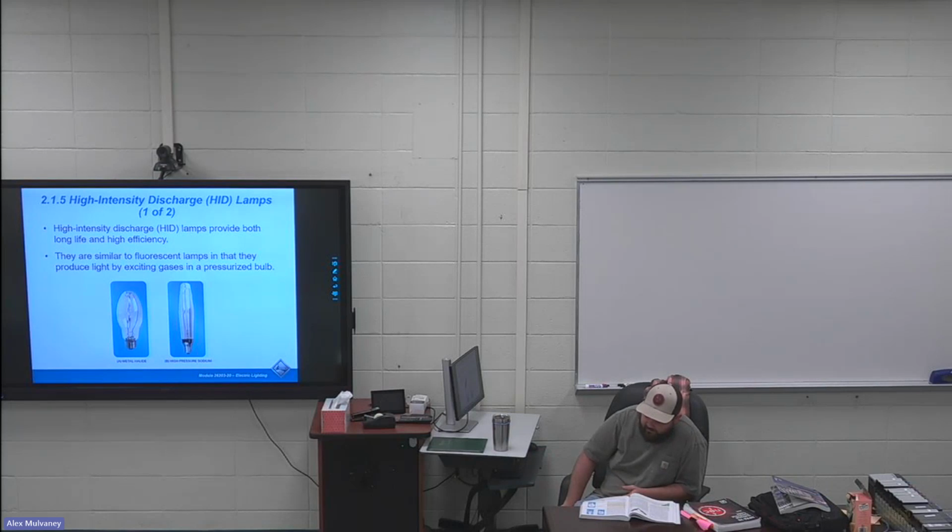Skip a sentence and I have the third sentence highlighted. Because of danger from arc tube rupture, NEC section 410-130F5 requires all metal halide lamps except thick glass PARs to either have a containment barrier, which is a lens, or be type O with a protected socket. So out to the side of that, I wrote explosion.